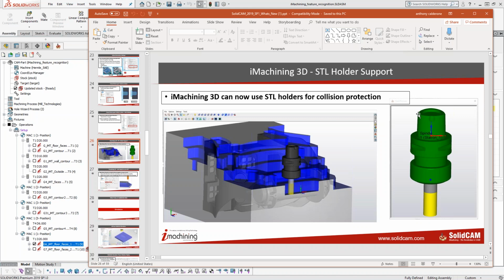So if you create some complex holder that's not cylindrical, like a rectangular one, you might think SolidCAM should be cutting more material than it is, but we make an envelope of the holder. It's not exact, and we do this for speed. So just be aware that it is an envelope, and it now works.